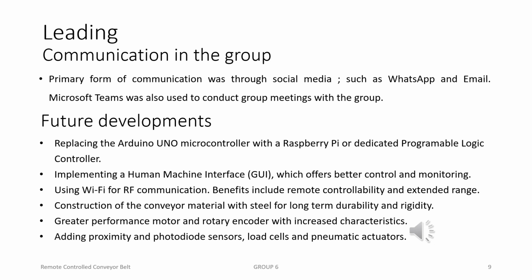Construction of the conveyor material: steel for long-term durability and rigidity. Greater performance motor and rotary encoder with increased characteristics. Adding proximity and photodiode sensors, load cells, and pneumatic actuators.